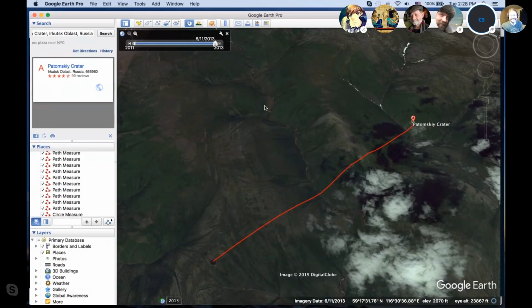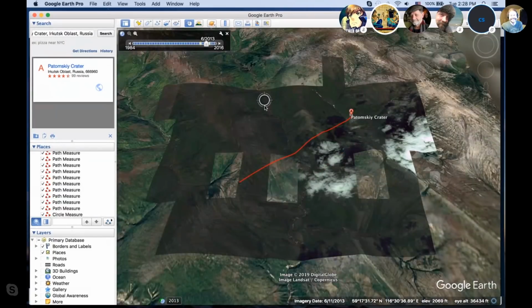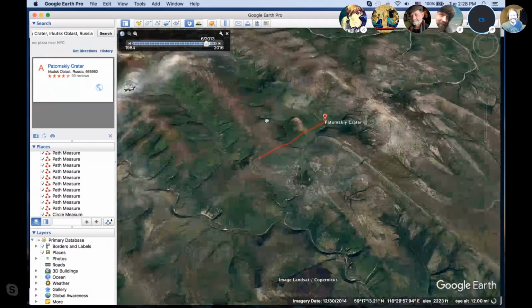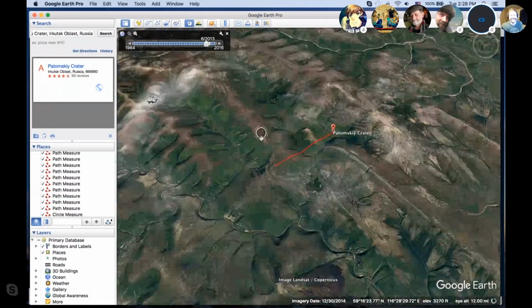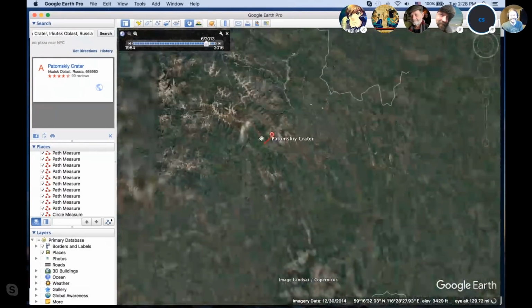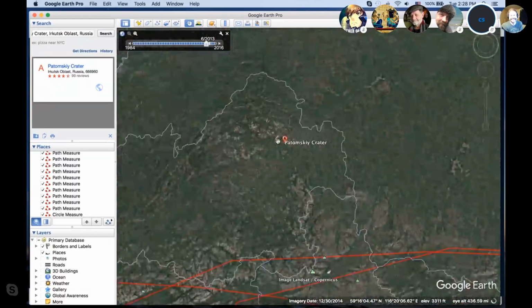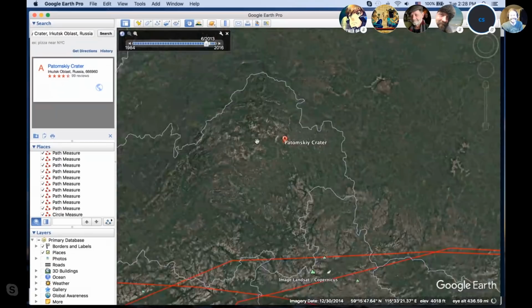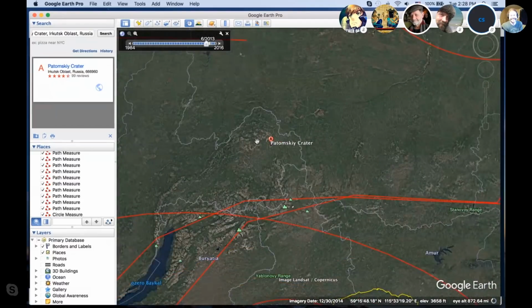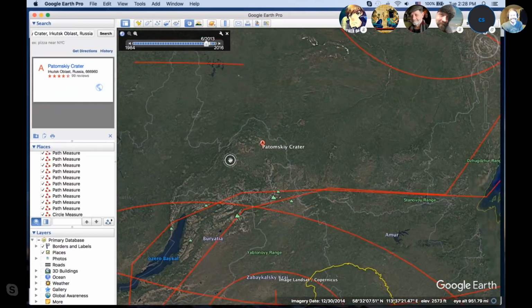Well, there is that loop idea with Andy Hall, which is supported by not only the evidence, but we recognize that loop currents are the thing that happens. Even Mr. Carrig was talking about the other day when we were talking about the step currents when lightning strikes the ground. The width between your feet determines how likely you are to be killed. Yeah, exactly right. Because it's the loop that goes through your legs, up through your torso, and back down that will kill you. If your feet are together, you're just one thing, so to speak, electrically.